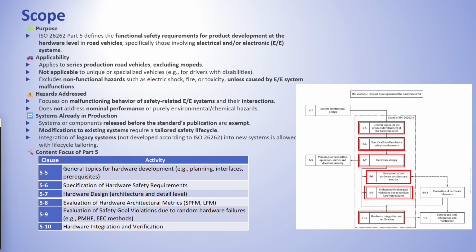Testing, testing, testing. What kind of hardware are we talking about? Does it cover everything from a simple resistor to a complex chip? It does, yeah. And that breadth is really important for safety. It applies to non-programmable hardware, your basic resistors, capacitors, that sort of thing. But it also applies very much to programmable hardware, things like ASICs, application-specific integrated circuits, custom chips, FPGAs, field programmable gate arrays, and PLDs, programmable logic devices, all that complex stuff that has safety logic embedded right in it. It ensures everything gets looked at.